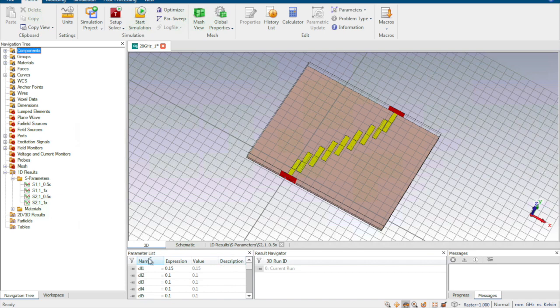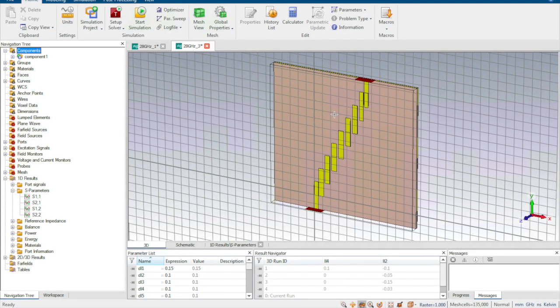So I optimized it and saved it as another design. I will show you the optimized results. I spent a lot of time to optimize this filter, and I followed two principles. First, since we want to move the center working frequency from 27 to 28, I made the length of the microstrip line for each stage a little bit shorter, so its working frequency can go a little bit higher. Another thing is I want the magnitude of S21 to be as high as possible.